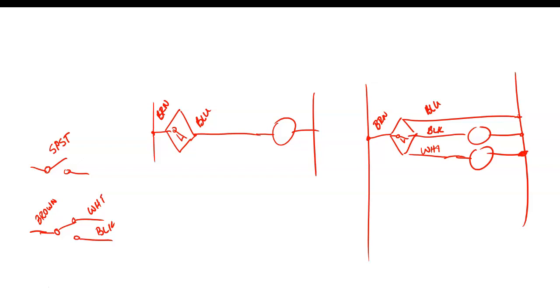You understand? It's DC. We don't have to convert DC back into DC, right? So the preferred method in the industry is your programmable controllers are going to operate off 24 volts. Now these solid state sensors cannot afford to drop 4 volts, right? So that's why most of your solid state sensors that we operate on 24 volts will be 3 or 4 volt sensors.